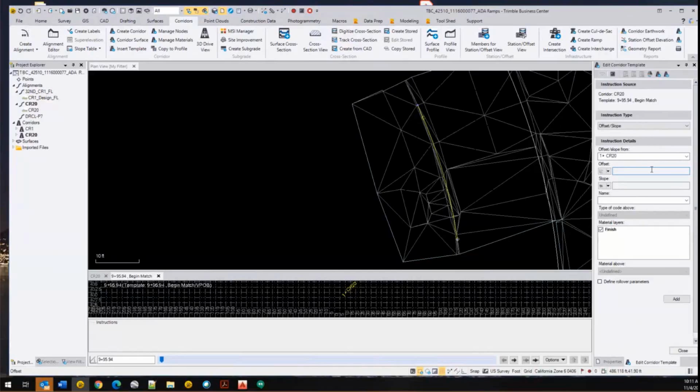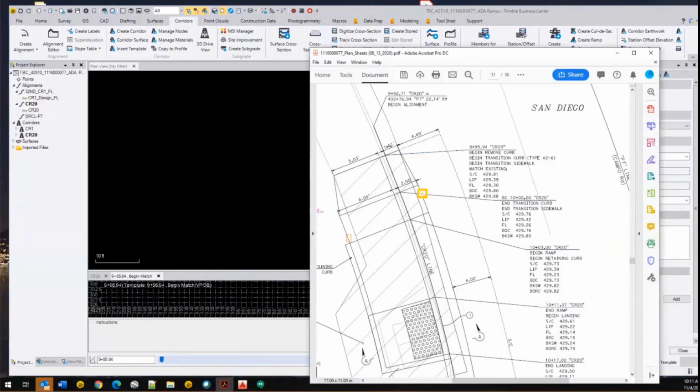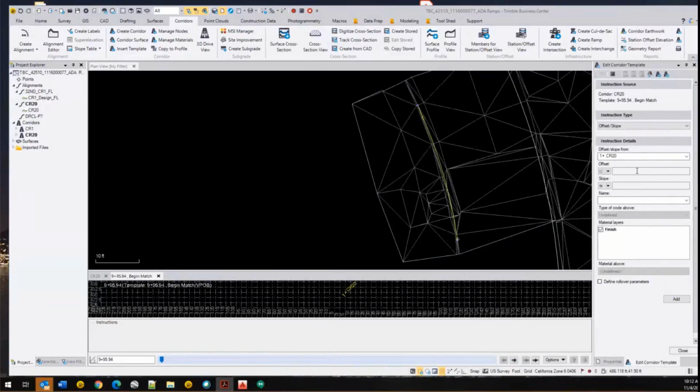Our offset is going to be, you know what's going to mess me up on this? I'm sure it'll get me, is that when we go to the right on the page, we're going left on the alignment. I know I'm going to mess that up at some point. So I'm going to go minus 151 in offset.